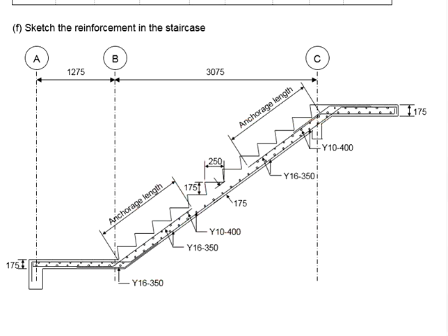throughout the entire staircase. For the bottom bar, you will have the arrangement in this manner. The longitudinal rebar will be placed closer to the soffit, whereas the secondary reinforcement will be on top of the main reinforcement.